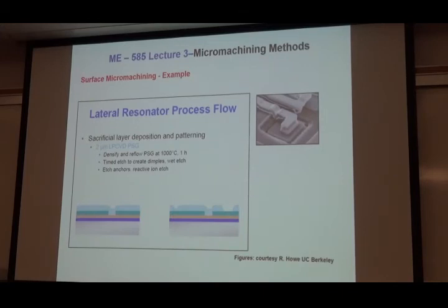Yeah, both of them are timed, but what you do is, I skipped 2 things here, right? So the first one, I cover this guy. I'm going to have a photoresist everywhere. And then I'm going to get a mask and expose only these 2 parts, do my thing, then strip the whole thing out. Because when you're digging, this is about 0.6 micron.